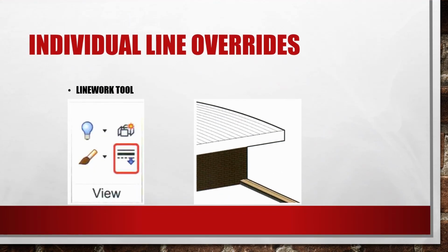Individual line overrides. Let's look at the Line Work tool. The Line Work tool offers the highest level of graphical control. It allows individual edges to be modified in a view. Common uses include removing unwanted joins or highlighting edges. These overrides are view-specific and purely cosmetic.